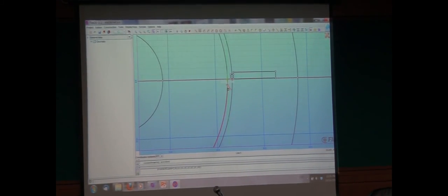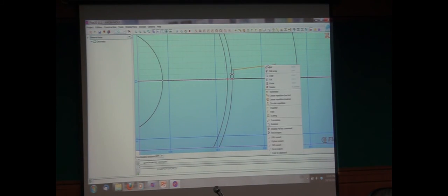No, the slot is not the shape normally. Maybe it's going a little, and by the way, if I don't like it, I can always move the line here, okay? I don't have to stay with a rectangular element, because the slot would not be a rectangular element, and then I can basically create a tilted part. So the slot is actually not square at the bottom. So here we're going to put a fillet.